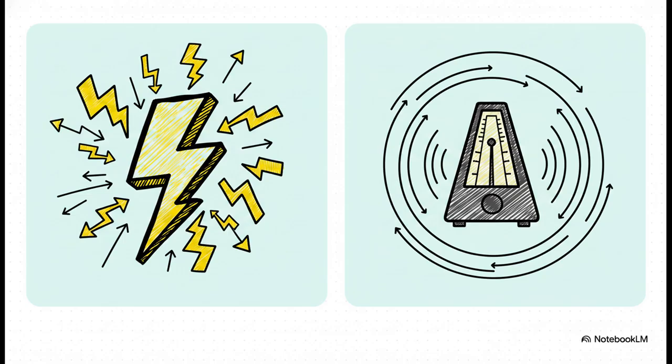Synchronous circuits, though, solve the chaos completely. They use a common clock signal to synchronize all the memory elements at once. Think of this clock signal as the heartbeat of the system, or like the conductor of a giant orchestra. While it might make the overall operation just a tiny bit slower, because the circuit literally has to wait for the next clock pulse to act, it absolutely guarantees a reliable, predictable operation every single time.